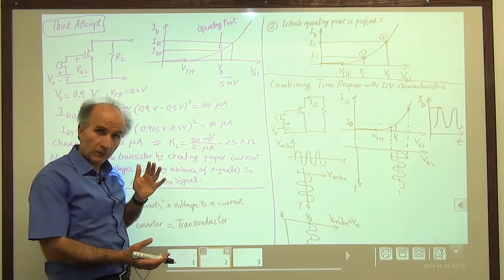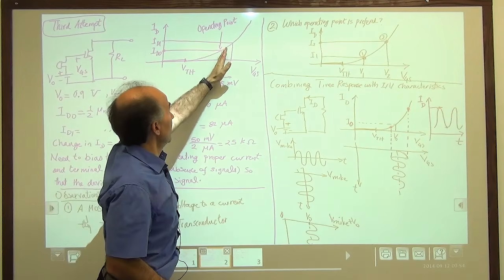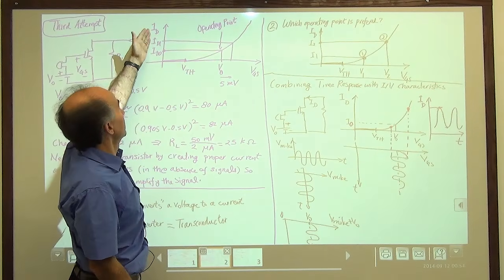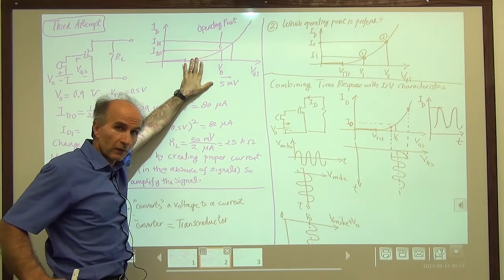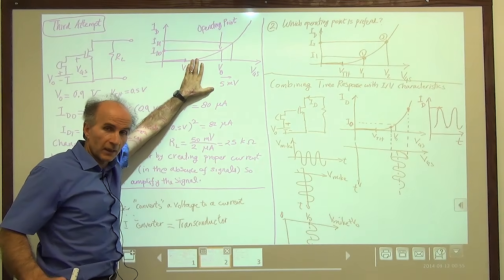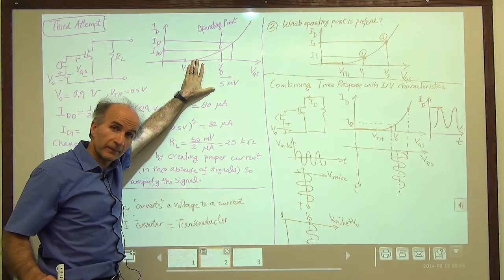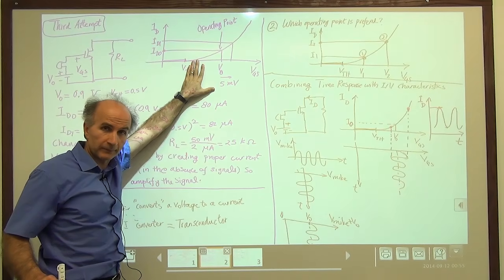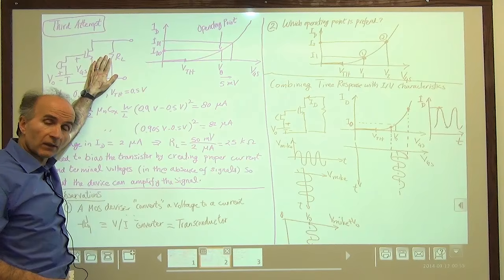We took care of the gate source voltage, right? We applied the battery here, chose it to be this value, and so on. And I just drew ID as a function of VGS. But remember, for the device to be in saturation, the drain source voltage also has to be some value, right? It cannot be too low. If it's too low, then we have a problem. How much is the drain source voltage here when there is no signal?